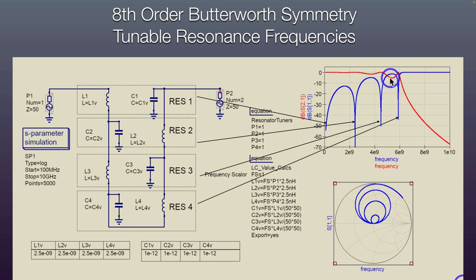And you can see on here that these have unequal ripple in this case, and so we get a big ripple out here at the highest frequency. That's the outermost ring on here. You're starting off with DC in the very middle at the 50 ohm point, looping around for the first resonance, second resonance, the third resonance, working your way to the outside of the Smith chart.